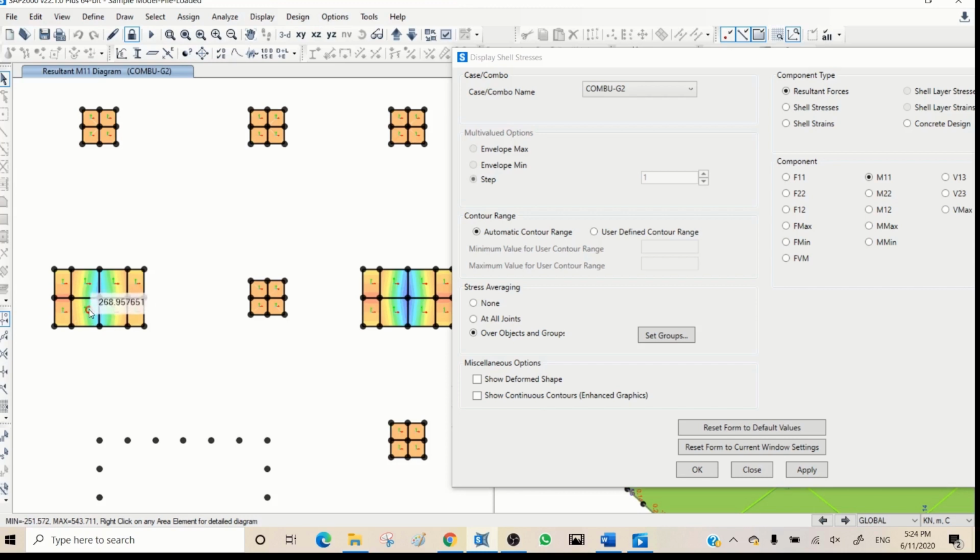Here is the column, so the moment is positive. You come to the pile, the moments become negative. So this is the way that moments move. Yeah, so this is along 1, and the same for 2-2. You see the other way, but because you don't have support here, you don't see that kind of regular arrangement that we saw. But here you can see the moment is negative and then going to positive. So that's how it works.